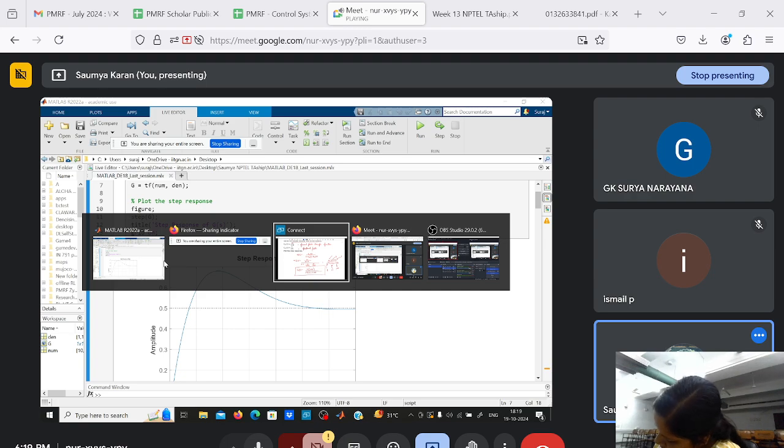Okay. Then stability range. When is the system stable? The system is stable when all closed loop poles have negative real parts. That means with the increase in gain from 0 to infinity, it should not happen that the root locus is going in some other part, like the poles are traversing in the right half of the S-plane. If that is the case, then for all those values of k, the system is going to behave in an unstable manner.